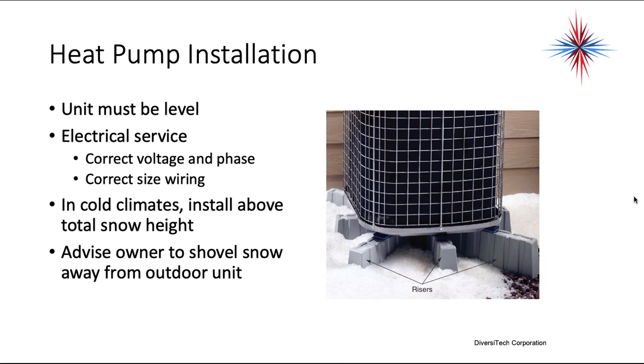In colder climates, you need to install above the total snow height. Okay, you want to make sure the owner knows to shovel snow away from the outdoor unit. We don't want this buried in a snowbank. Now, in the warmer climates, especially in the south, along the Gulf Coast and along the oceans and along the beaches in the south, you have to worry about wind.